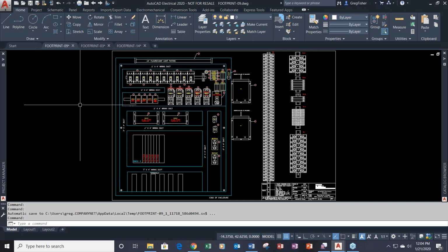And one difference between inserting a schematic symbol versus inserting a footprint symbol is that when you insert a footprint symbol, you're doing it via the part number. You're not just plucking from the icon menu and grabbing your block from there. It needs a part number to insert the footprint symbol. And there's multiple ways you can get there as well. And I'm going to talk about what I refer to as a four-step process.